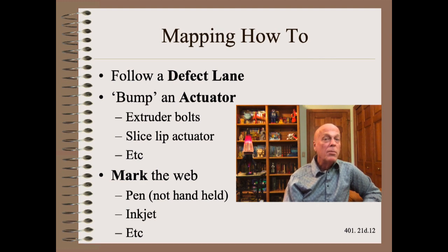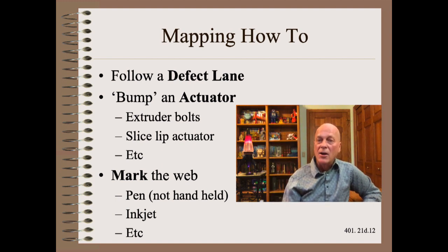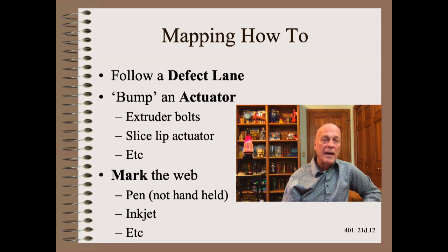Finally, the brute force method is to mark the web somehow. Please, for safety's sake, avoid handheld markers. Instead, set up a chemically compatible marker such as an inkjet that can be remotely actuated.